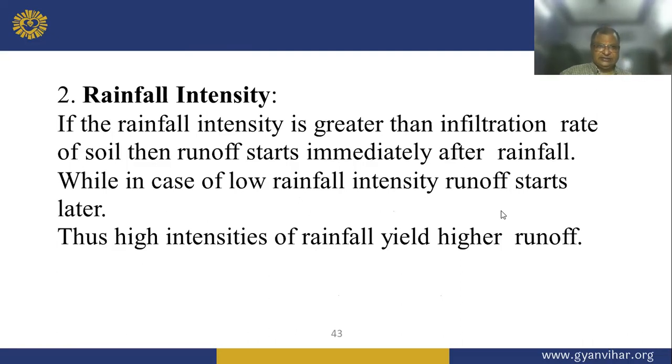Rainfall intensity. If the rainfall intensity is greater than the infiltration rate, then runoff starts immediately after rainfall, while if it is lower, the flow starts later. So high intensity rainfall tends to produce higher runoff.